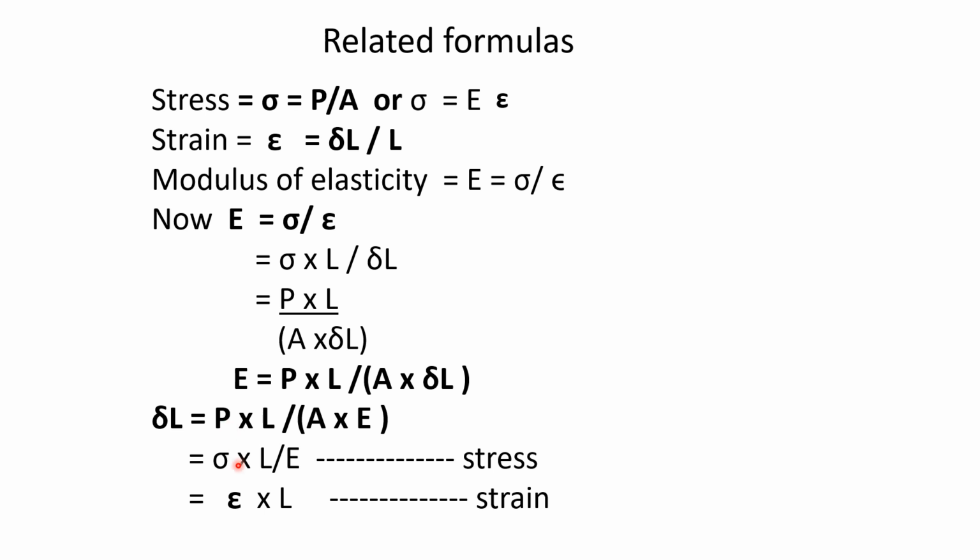If we know the stress, we can use the formula sigma into L upon E, that will give me the change in length. And if I know the strain, then I can use strain into the original length L, that will give me delta L. So these are the formulas which we have to remember to solve the problems.